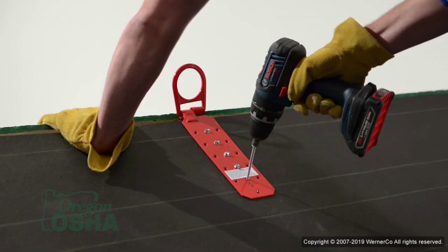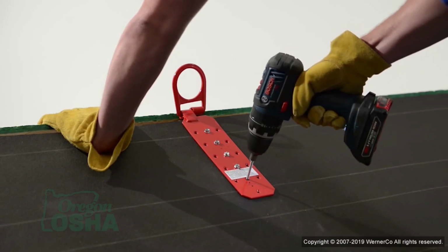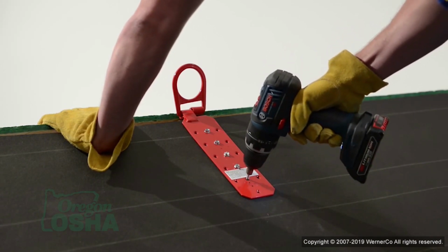When it comes to your anchors, there are a lot of options to choose from. And again, you have to choose the right product for the right installation, with the right customer and the right project, because you don't want to put an 18-inch tall, standard flat roof bracket on a pitched roof, because that's not OSHA compliant. So again, you've got to match the product with the project and then with the customer.